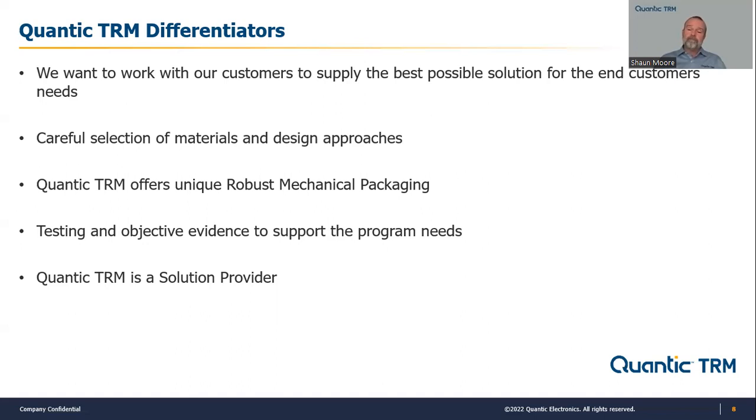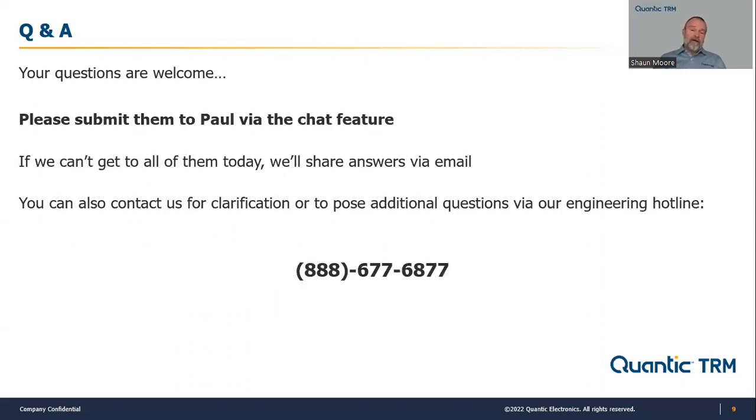Well said. And I think we have time for one question, and the one that should come in is, can I use screws to attach a larger surface mount device? The answer is yes, you absolutely can. The thing to be careful of, though, is, if the device is large enough where you have to screw it down, whether or not the board that you're screwing it to will survive things like vibration. Usually, when you get that much mass on a PCB that is unsupported, you can very often lead to some vibration failure. So be very careful about that.